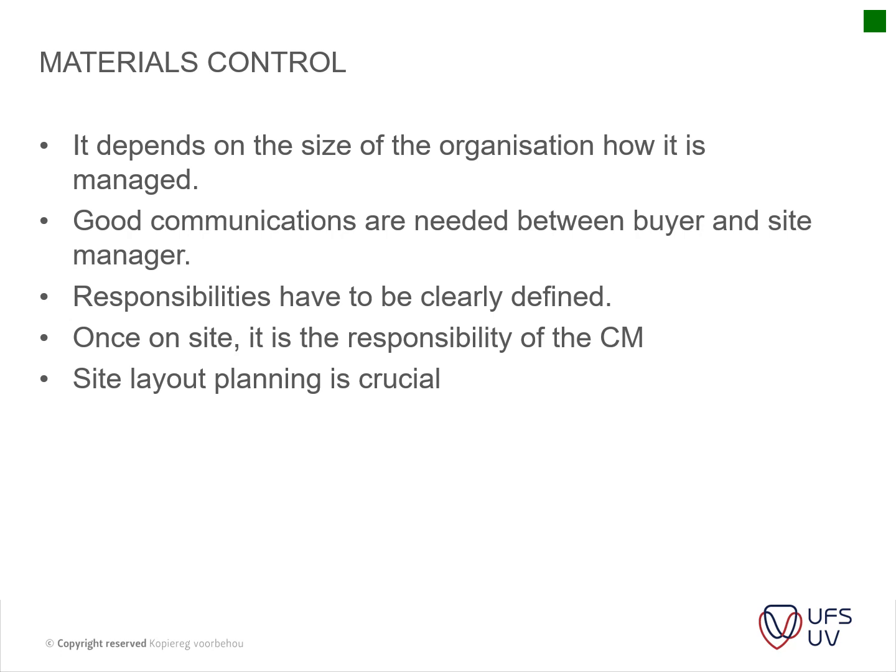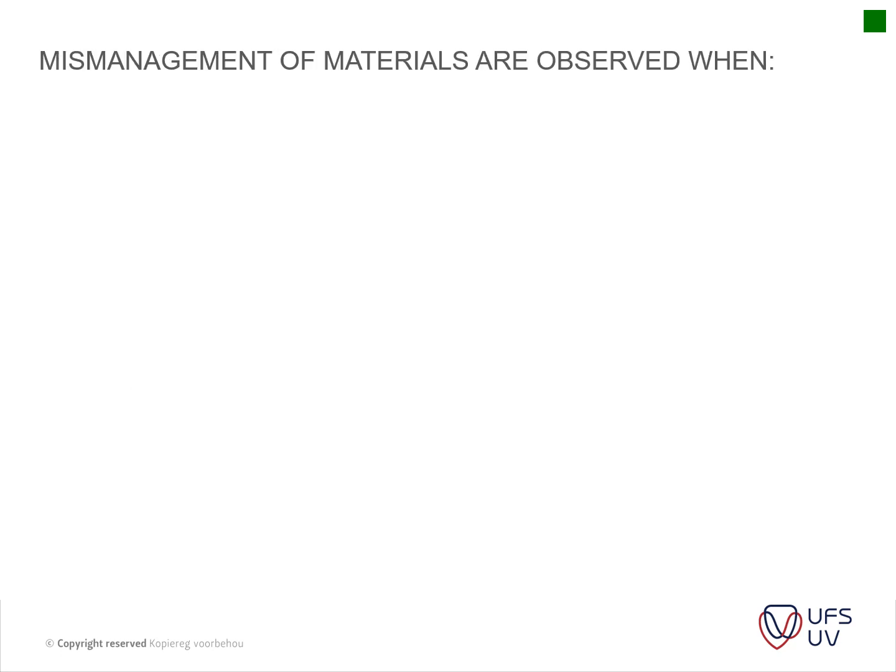And then site layout planning is crucial. That's where you're going to put your plant, where you're going to store your materials. And I think it's one of my next slides. There's a couple of things that you can see immediately. If the housekeeping on site is done well, if you come onto a site and you see everything is nice and neat, you know they're managing their materials well. If you come onto site and you're falling over debris and bricks, broken bricks and so on, you know that they're not managing their materials very well.